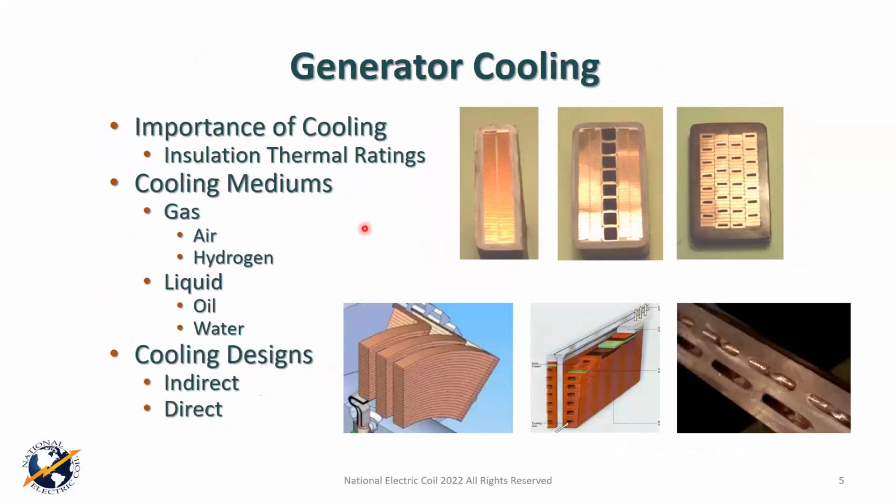Before we get into the different components, I think it's an important thing to understand. One of the most important aspects inside of a generator is cooling. And people say, well, why is that? Well, obviously we want to keep it from burning up, but more importantly, the lack of cooling, or let's say excessive heat, the other side of the coin, tends to deteriorate insulation exponentially almost, okay?